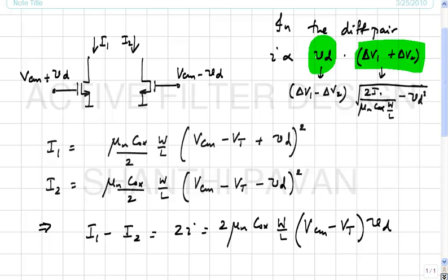Okay. You understand? So there is a lot to be said for this current source. Okay, though it may not be immediately apparent, right? This current source got many problems as far as linearity is concerned, but if you are not careful with this, you will almost always end up with the gyrator, I mean, the transconductor may look fine, but the gyrator will oscillate in the common mode because of the positive feedback.